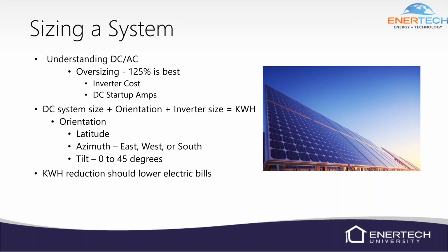And then tilt is 0 to 45 degrees. We've done installs where we're completely flat, and then we've done 45 degrees, which would be like, I don't know, a 12 pitch? It just depends on where you're at and what's going on with your climate as to what's the best angle to go. 45 degrees isn't going to be very good in the summer months, but it produces an awful lot in the winter because the sun's so low in the sky.